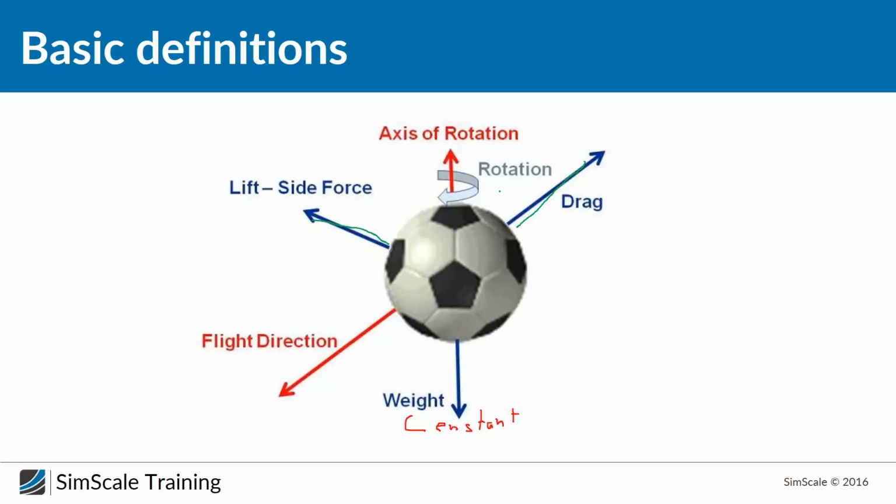And as long as a smooth ball has no spinning, we have only drag, and components like lift and side, since it's a symmetrical case, will not appear. But as soon as I'm adding a rotation to the ball, I will also get these lift and side forces.